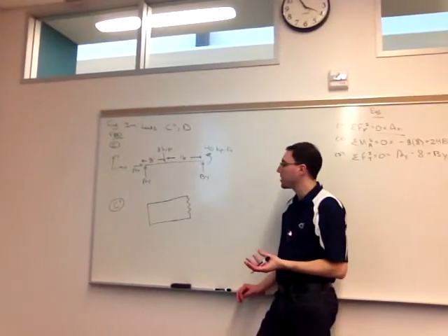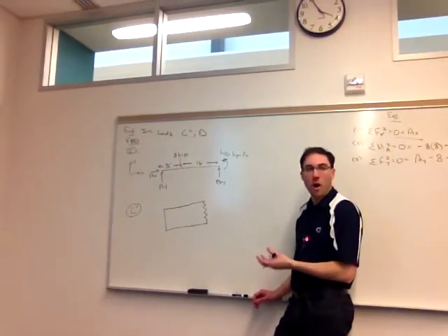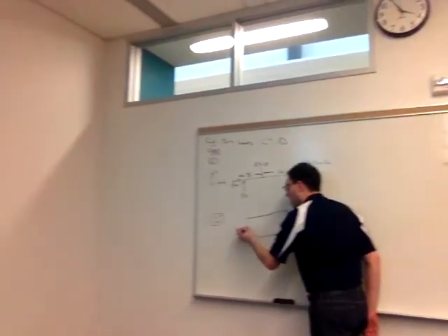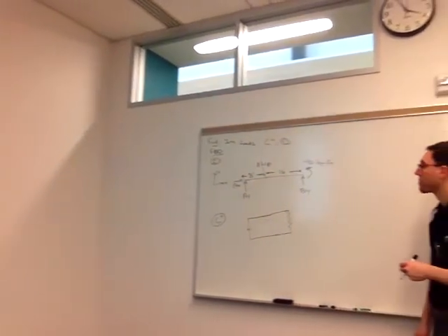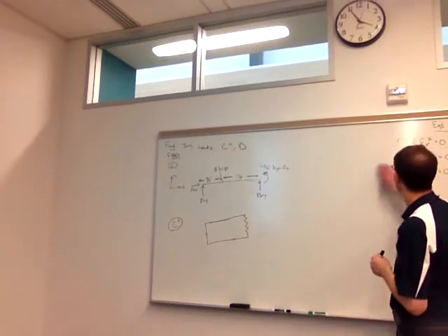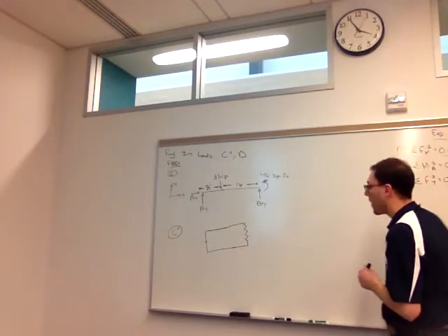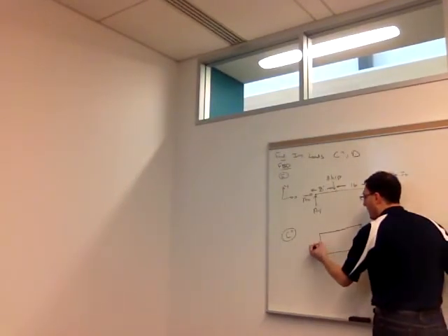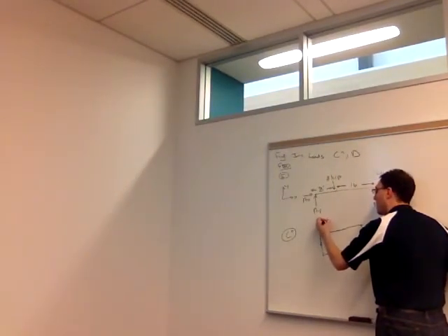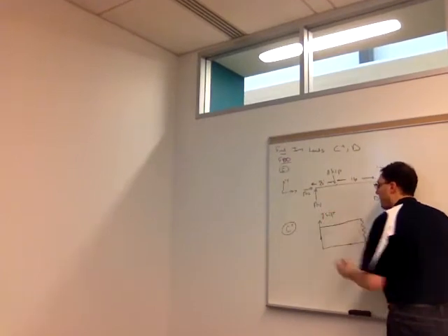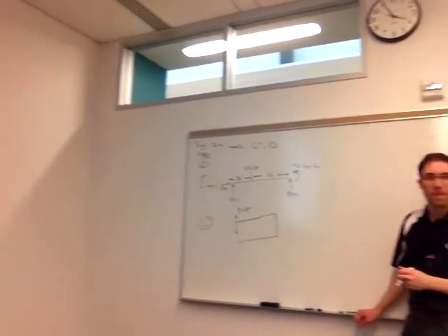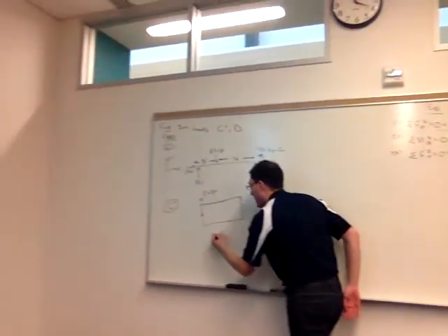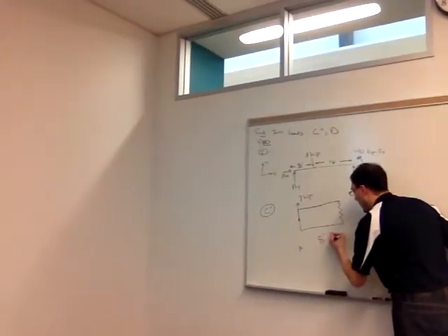Like we saw with method of sections, I'm going to copy exactly all of the external forces that are acting on the structure, just the piece that I kept, though. AX and AY are acting on it. I found AX was 0. AY was 7 kip up. So I include that in my free body diagram. Nothing is happening over here. This is 8 feet from A to C.